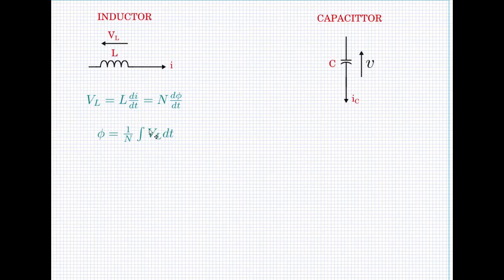which means this volt second has to be balanced, as I had been discussing earlier. So in the inductor, it is very, very important that you know there should be volt second balance in the steady state.